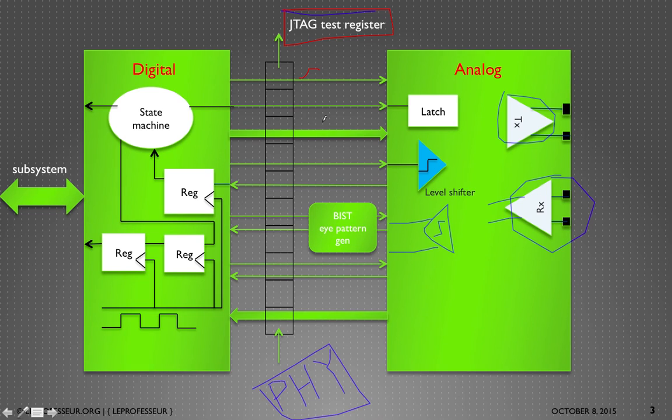This is, say, a bus. In a bus you might be interested in one or two signals, but may not be interested in monitoring other signals, so you can leave those out. But the control signals are a must to observe, and you can do that by data test registers.